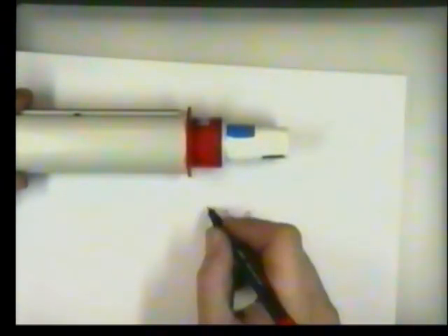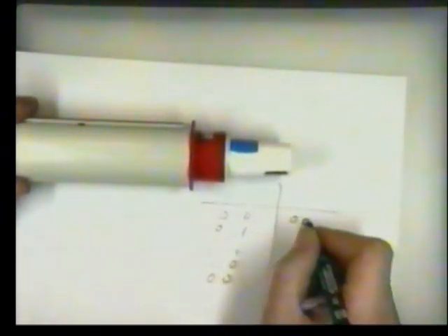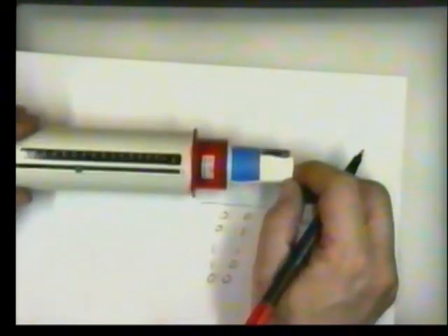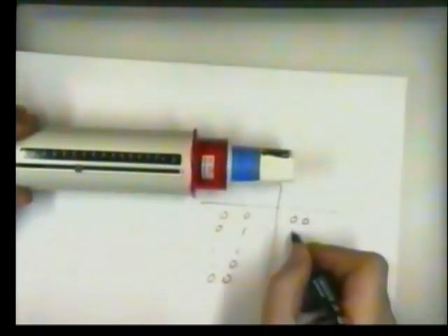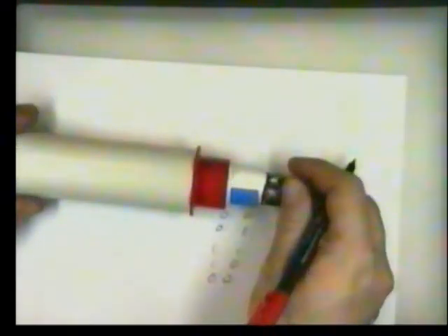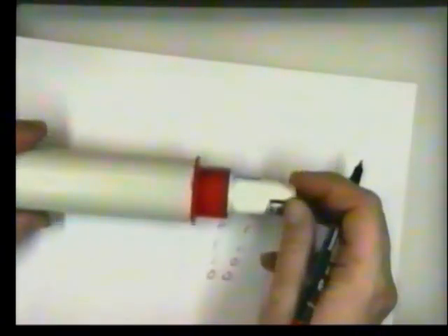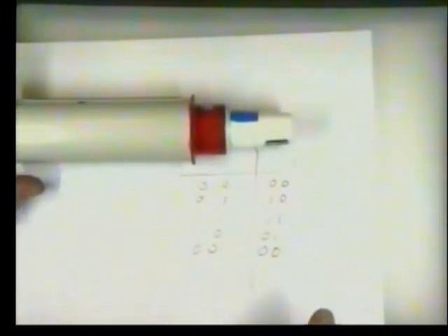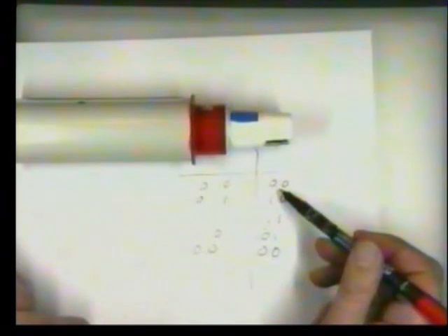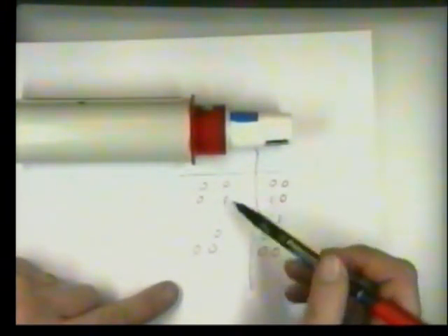You get a totally different pattern, and believe me you do, I'll show you, when you rotate the other way. If we started from 0, 0 and we're rotating in this direction 1, 0, then we go to 1, 1, then we go to 0, 1, and now we're back to our rest position 0, 0. And there's the proof of it. This sequence is totally opposite to that one. It's the reverse sequence, but you will never find the same transitions.